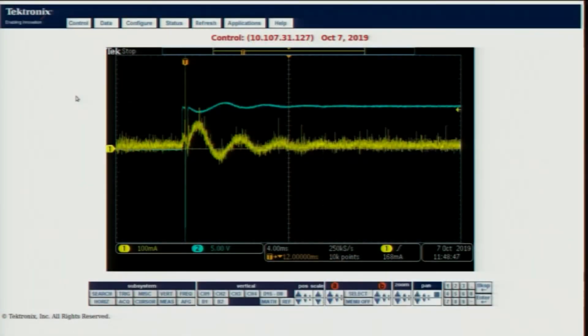As before, we saw that when you switch on this circuit, it is not a very smooth step, probably because of two reasons. One, the switch is not a perfect switch, it does not switch on instantaneously. There may be a bit of bouncing, in the sense that it does not make perfect contact instantaneously. And the second thing is the parasitics, because this circuit is forming a loop. You have got parasitic inductances and capacitances, which we discussed in a few classes before this.